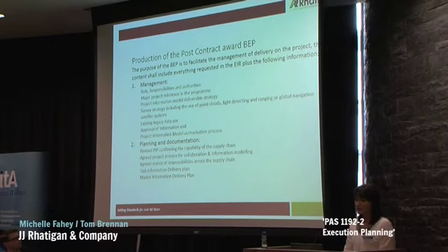Under management, you have the roles, responsibilities and authorities, the major project milestones within the project, the project information model delivery strategy, the survey strategy, including the use of point clouds, light detection and ranging, and global navigation satellite systems, existing legacy data use, approval of information, and the project information model authorization process.